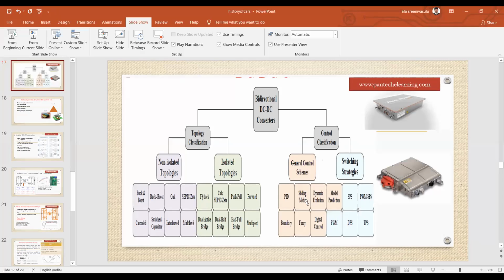While we are working on the prototype board, mathematically, by using the mathematical equations, when we give an input voltage of 12 volts and turn on the switch at 50% duty, you will get 24 volts of output voltage. That we can derive theoretically also. The same concept, when we design the model in the loop, we apply the closed loop feedback system also. Here we are adding the capacitance, and by adding the capacitance we can minimize the ripple. That I will show when we design in MATLAB SIMULINK software.